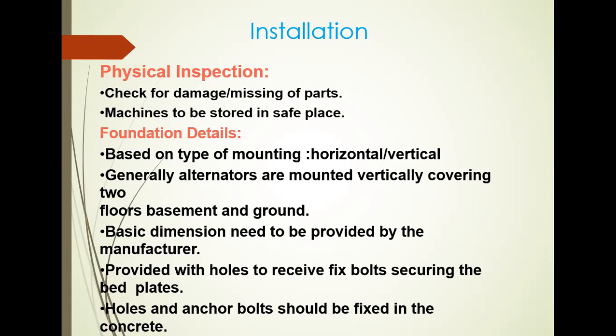For foundation, based on the type of mounting, horizontal or vertical, generally alternators are mounted vertically, covering two floors, basement and ground. So we have two types, horizontal mounting and vertical mounting, based on the machine.